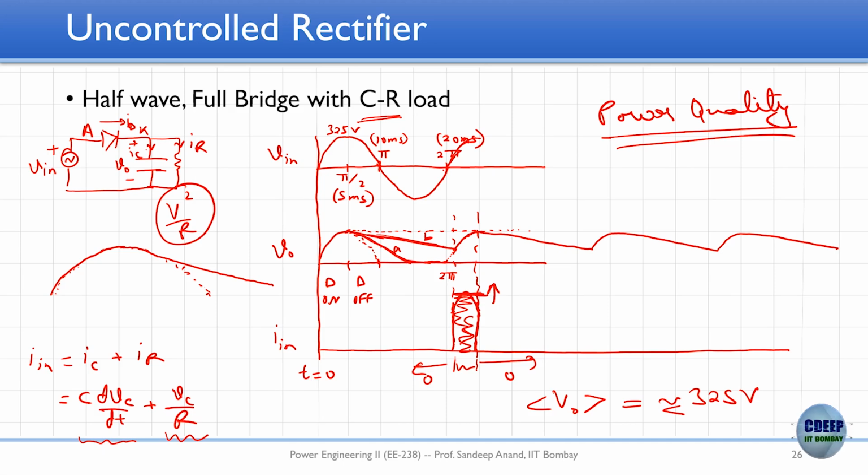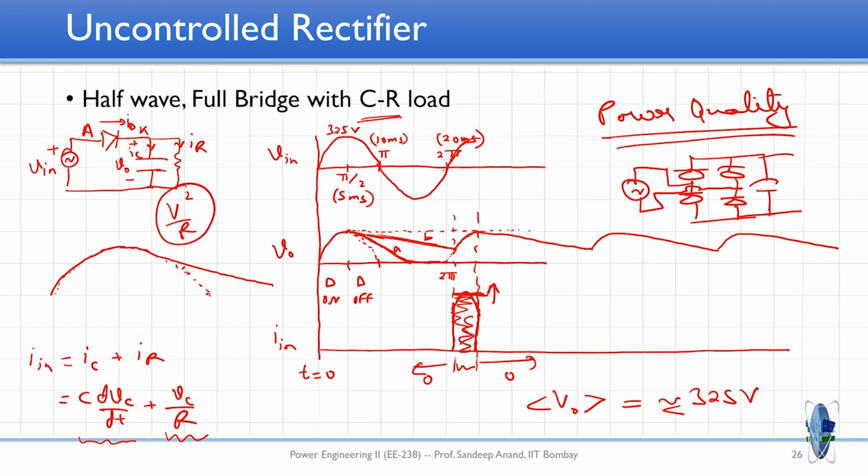Alright. In reality, this is the circuit which gets used in most rectifier circuits, not the half wave one, but a full bridge followed by a capacitor. Full bridge followed by capacitor, right? So you have this full bridge circuit followed by a capacitor. If you look at your mobile chargers, this is the circuit which is used, and of course this then goes into different sorts of loads and everything else within the mobile charger.